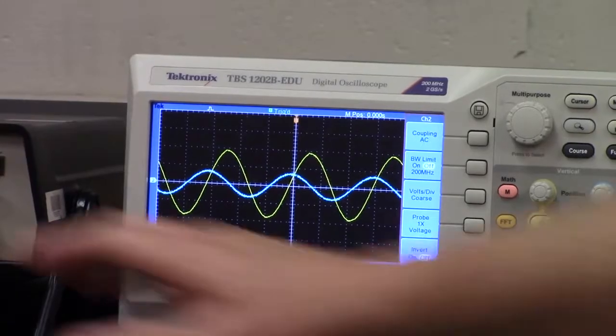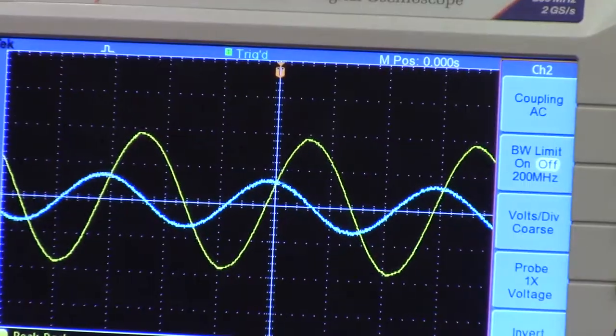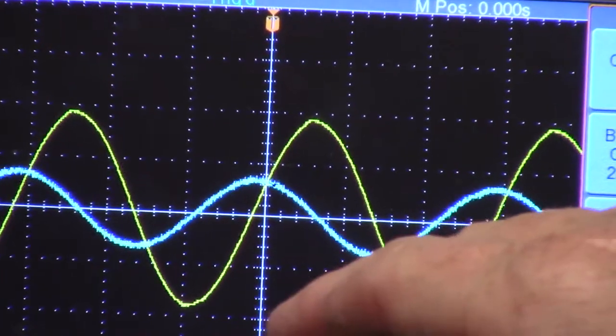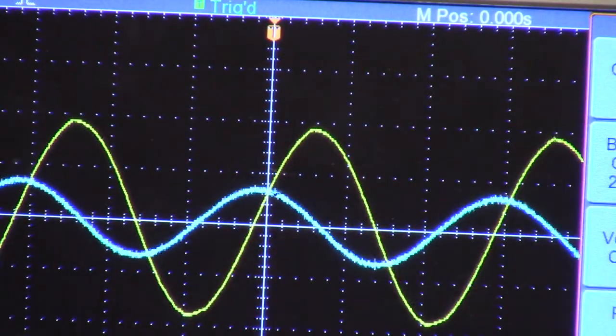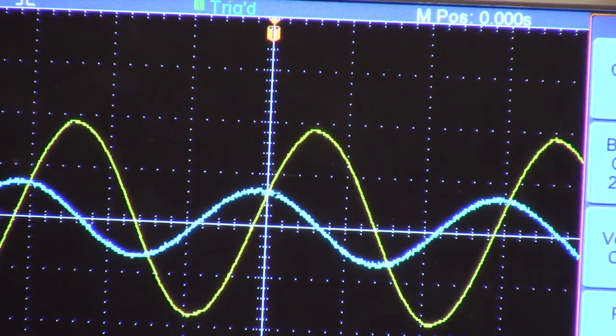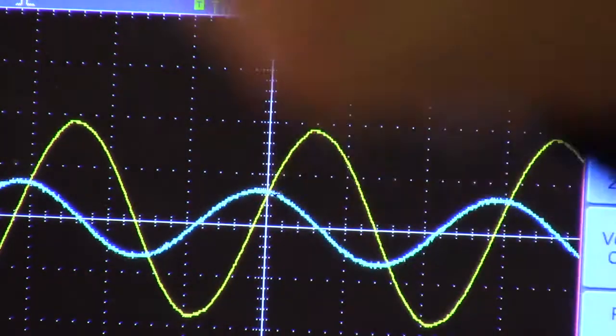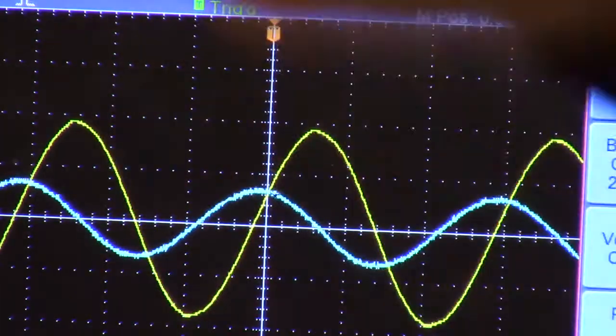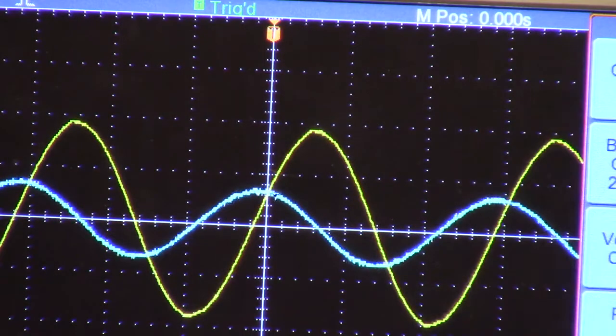So I'm going to turn it down to about a frequency of 331. And if you take a look here, you'll see that again, they don't match up. And again, the blue one this time matches or peaks before the gold. And so in this case, I have current before I have voltage or EMF. And so that's the I before the E with the C in the middle. So there's my ICE. And so you see both of those.